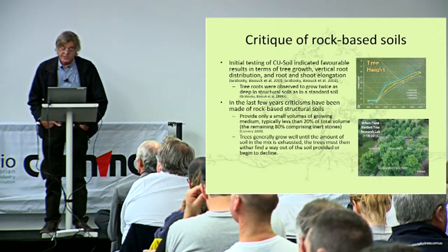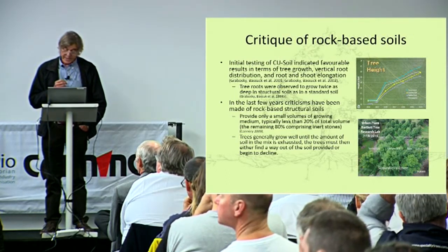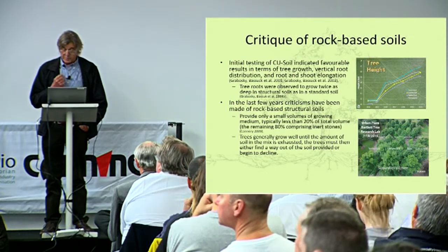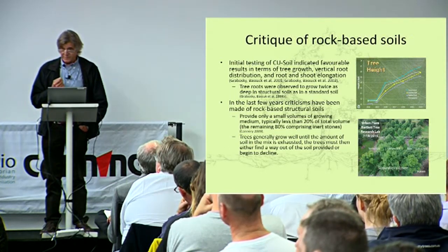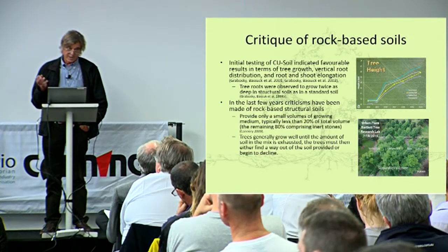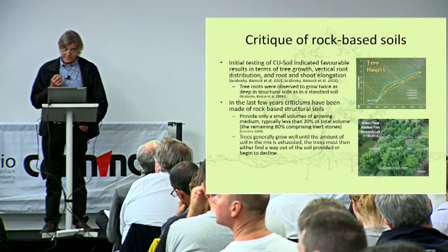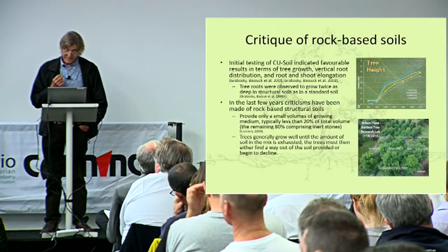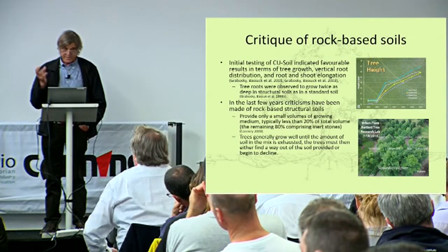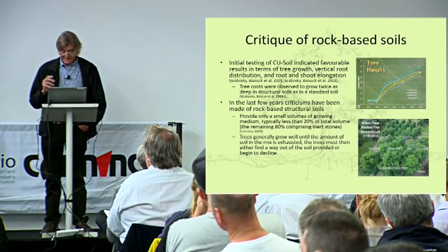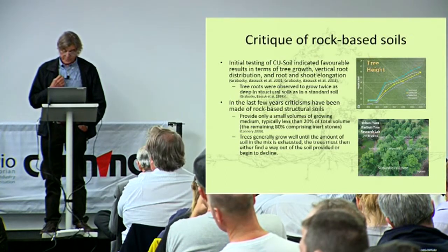There's been a critique of these rock-based soils in the last few years. Once again, here's this image from the Bartlett Tree Research Lab. The main problem with rock-based structural soils is that the trees grow really well for several years, and they exhaust the resources within the soil, which is only 20% by volume of the total volume. And after that, the trees struggle to survive. There are other issues as well. How do the tree roots grow within those rock voids? Do they have the fertiliser and other resources for long-term growth?